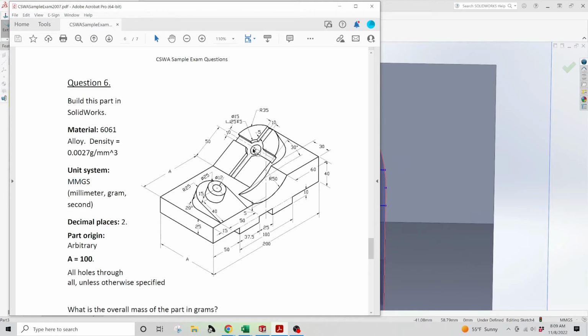There's a 25 and a 15 is what this is trying to tell you. So you have a diameter of 15 down below the 25 here at a 5mm depth. We'll talk about how to recreate that, but we don't need some of this other detail. So we're going to do a 5mm cut of most of this geometry, and then we're going to do a through-all cut for this inner hole.